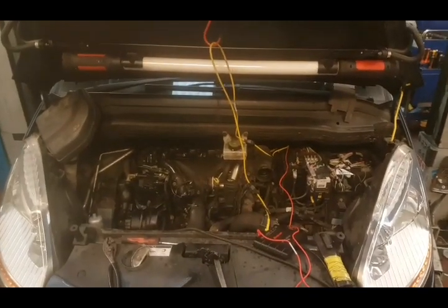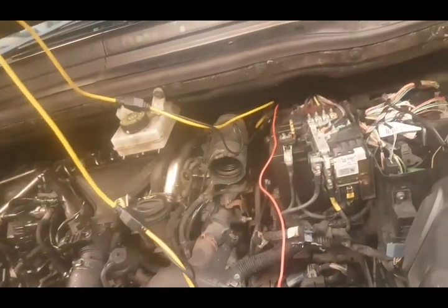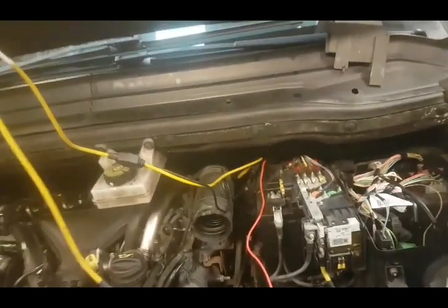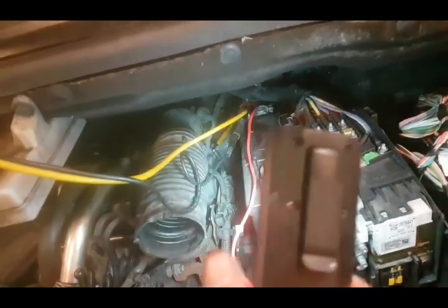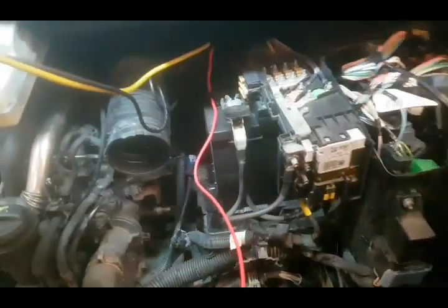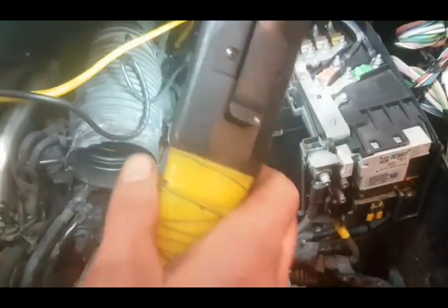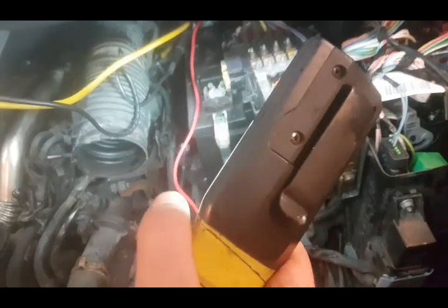So I stripped her all out to get access to just plug in the fuel pressure relief valve, or whatever you want to call it. Fuel regulating solenoid, I don't know, people have different names for them. Back there, I'm sure you can see where my pins are going in. I was going to scope it, but while I was there, as I had to have the battery and all that come out, I thought I'll just quickly, because it's only 2 Allen keys holding that fuel solenoid in place, pop it out and have a look. Popped it out, had a look, nice and clean, no blockages, bench tested it, it was working.